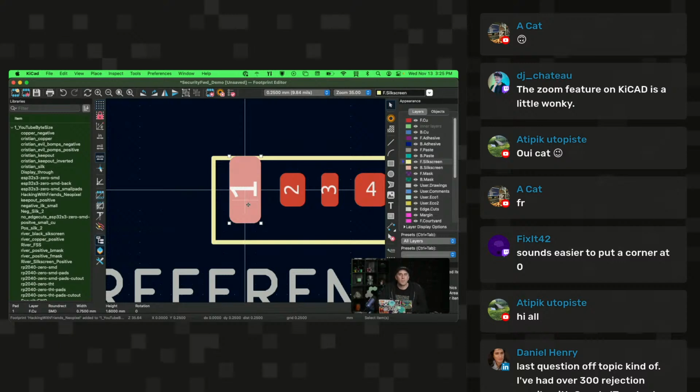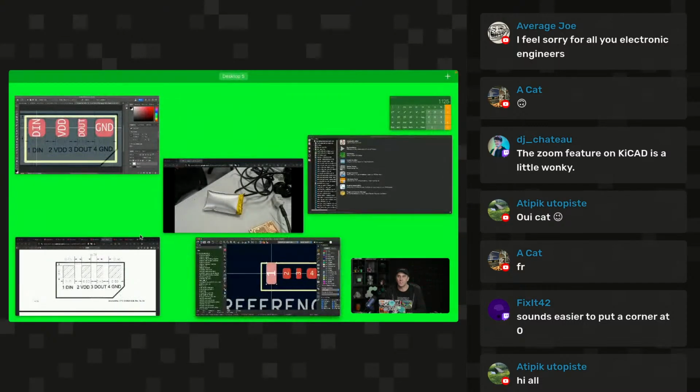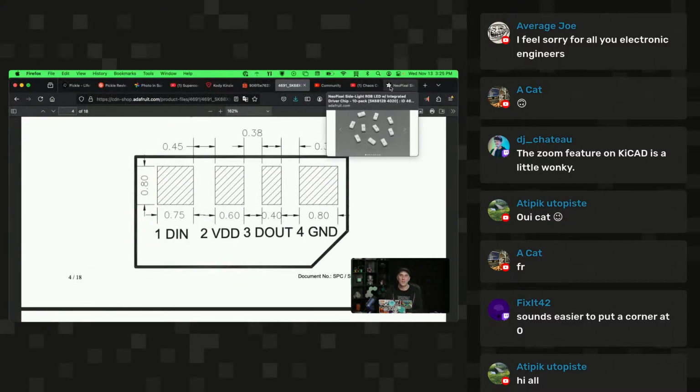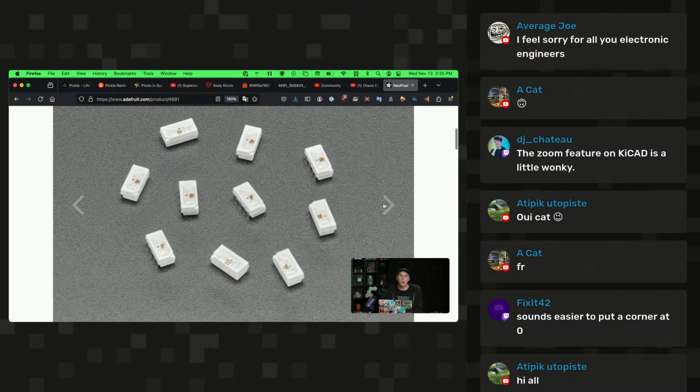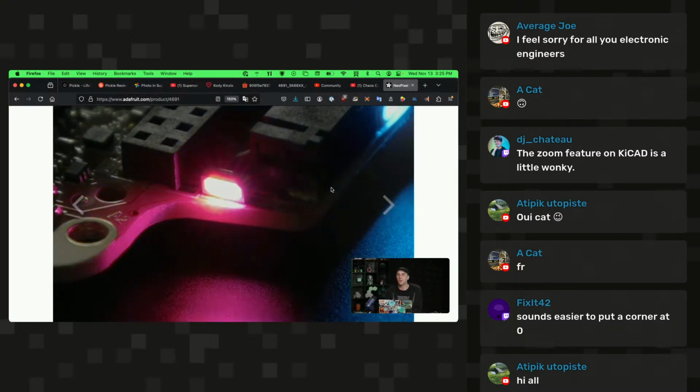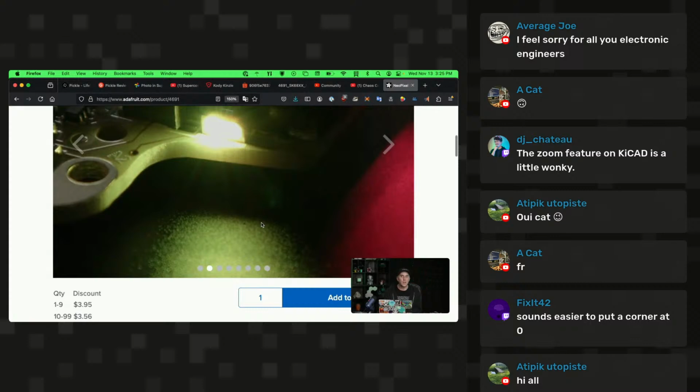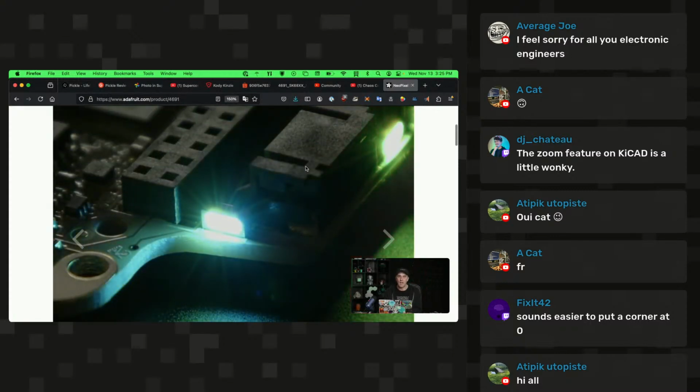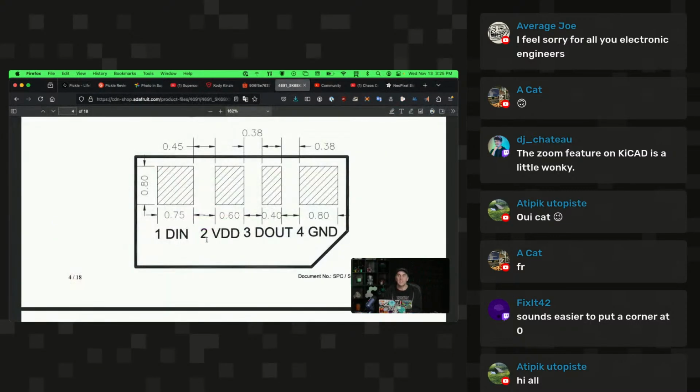So I talked with my friend about this, and they were like, yeah, you kind of just got to decide how much room you want to have to hand solder these, if that's what you're going to do. So for this little demo, I just wanted to say, if you get to this step and everything is properly aligned and you've made your own component off of a data sheet, which is the scariest thing to do here, then you can use one of these glorious new components that maybe you've seen other people use and you want to use for the first time. I need to go through and label which pins are which, but this should at least get the hardest part of the data sheet out of the way.